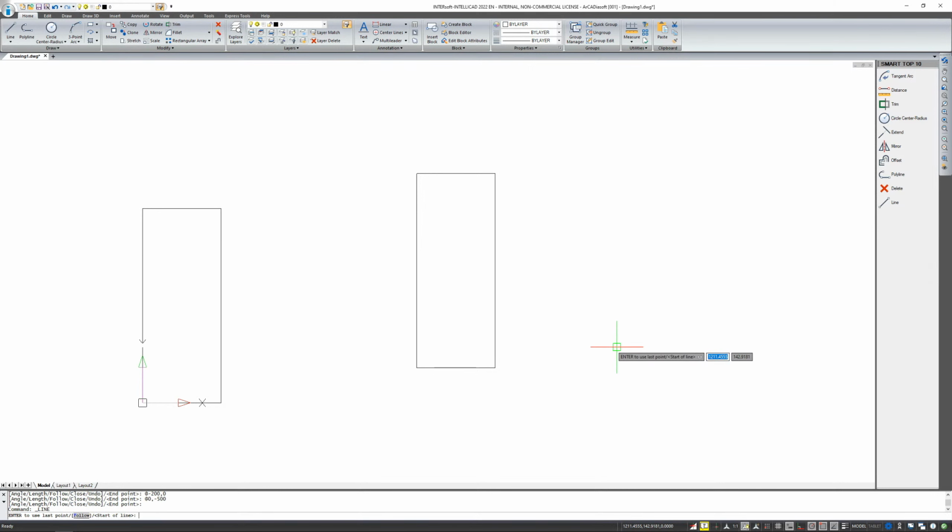When you turn on such a window, the window automatically switches to relative coordinates. That is, when I now click the starting point, I can already enter data from this point. Only I no longer need to enter the at sign. I draw the same rectangle each time I enter data without the at sign.